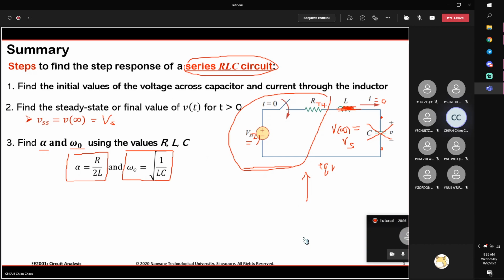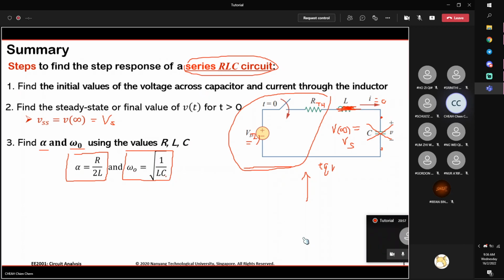If you have a complex circuit and you simplify it to this form, then this will be your equivalent values. Even the inductors and capacitors can sometimes be simplified. You have learned how to simplify series and parallel combinations of inductors and capacitors. This means I can simplify most of the circuits into this form so as to get the standard solution. And omega 0 is 1 over the square root of LC. Again, L and C could be the equivalent values.